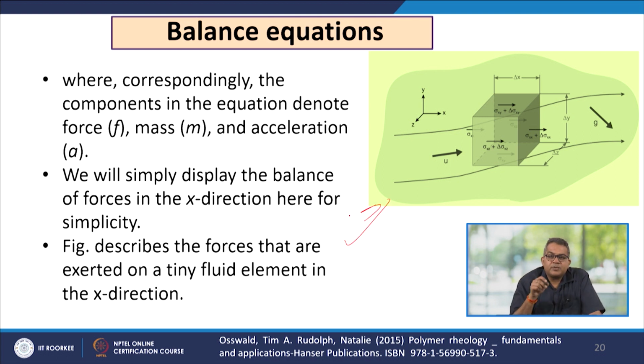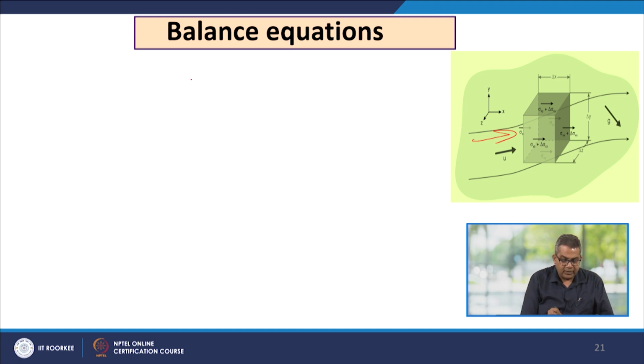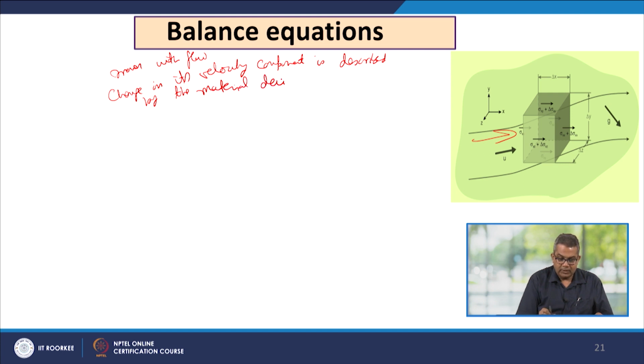Now, this figure describes the forces that are exerted on a tiny fluid element in the x direction. Because the element in this figure is a fluid particle that moves with the flow, the change in its velocity component is described by the material derivative.